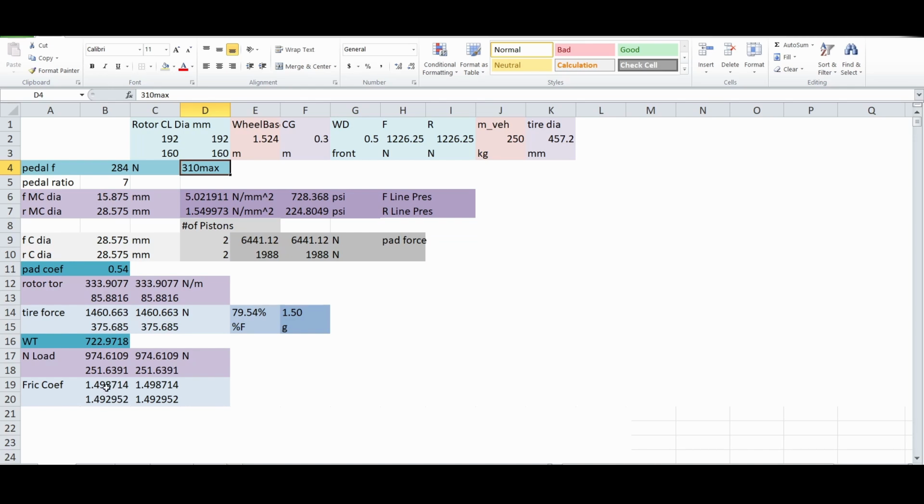So this is going to meet the limit of the tire before the rear, which I would always have the front lock up before the rear. If the rear locks up, you lose friction, it reduces. So the rear friction reduces, which could cause the rear end to come around and you'll spin out. So I'd rather have the front lock up and the rear not locked, so you have a stable platform because you still have rear friction.